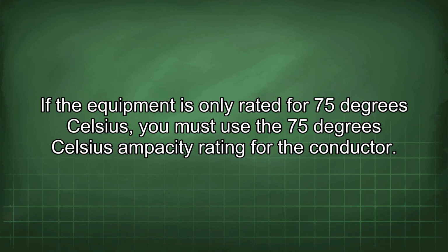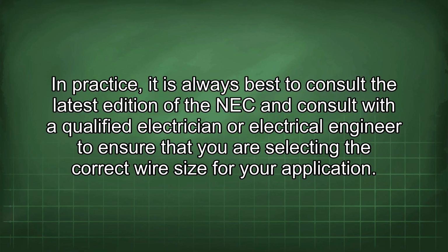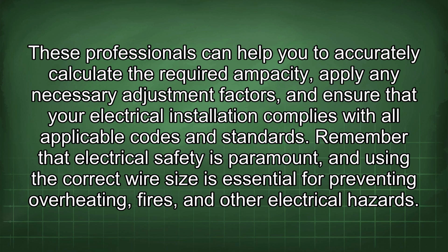In practice, it is always best to consult the latest edition of the NEC and consult with a qualified electrician or electrical engineer to ensure that you are selecting the correct wire size for your application. These professionals can help you to accurately calculate the required ampacity, apply any necessary adjustment factors, and ensure that your electrical installation complies with all applicable codes and standards. Remember that electrical safety is paramount, and using the correct wire size is essential for preventing overheating, fires, and other electrical hazards.